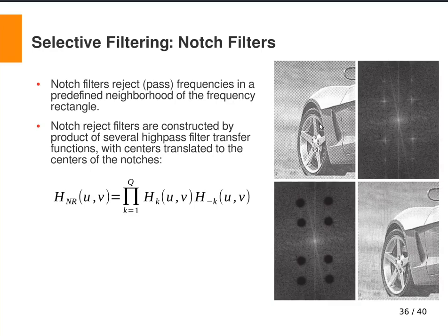If we calculate the Fourier transform, you see that we have these impulses, or bursts of energy, that are symmetric with regard to the origin of the frequency response. That is a common behavior because of the sine and cosine interference, because the frequency transform representation of a sine and cosine is two impulses that are symmetric with respect to the origin.